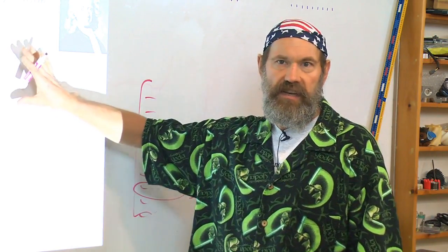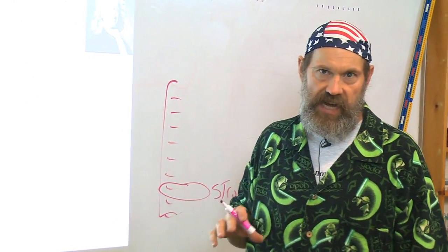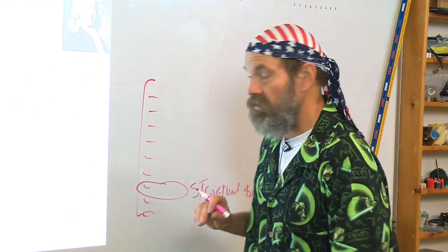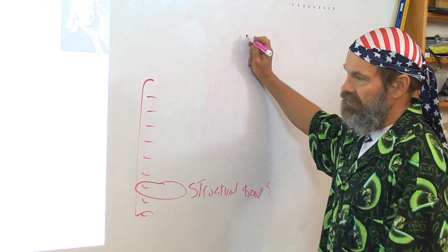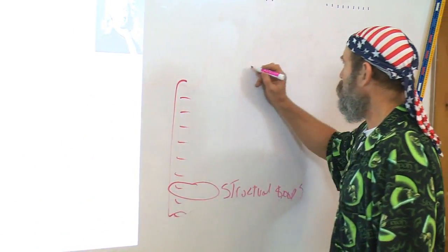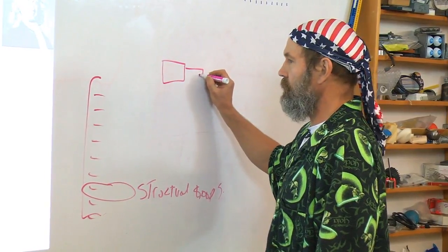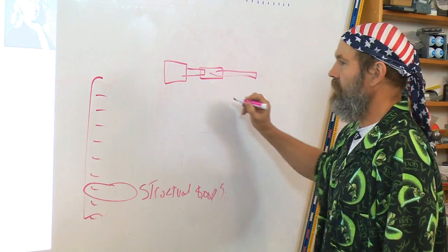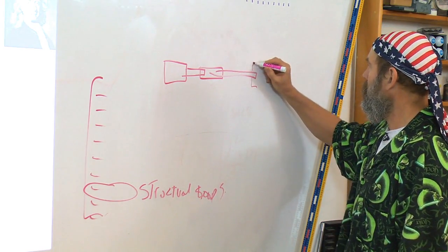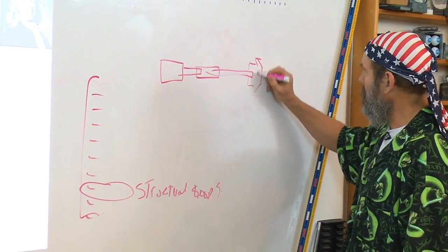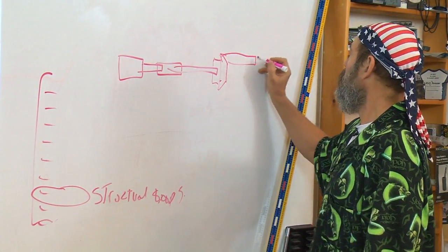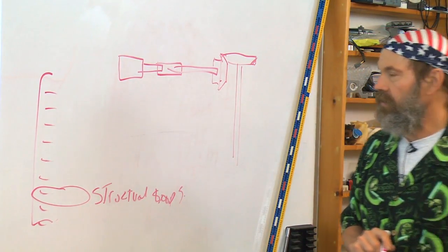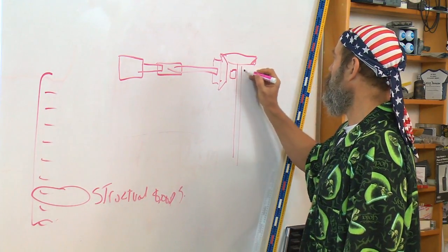So when you're looking at a machine, what's the purpose of a free body diagram in Newton? Newton, action and reaction. You push on something, it pushes back with an equal amount of force. So when I'm looking at this gear train here, for example, this person took a motor and they had this brilliant idea. Here was the motor shaft. Oh, and it wasn't long enough, so they put an extension on it to reach out here and to mount their gear on. Set of miter gears here. And they were doing this because they wanted to then transmit power down to another shaft. And this gear here was located in bearings.